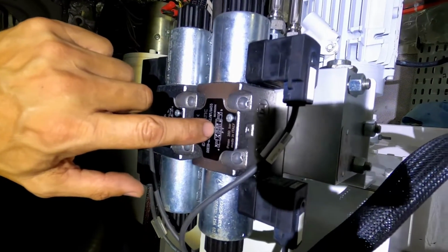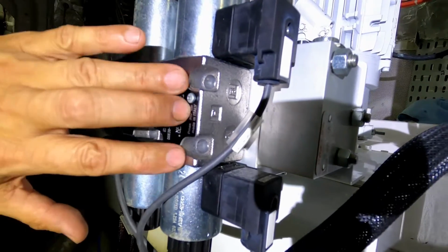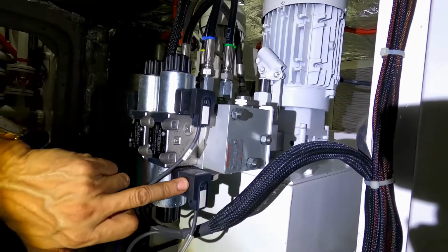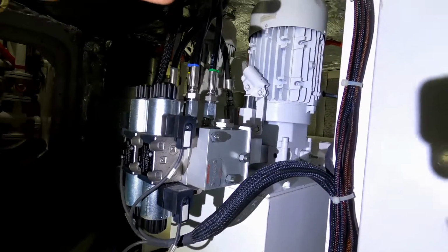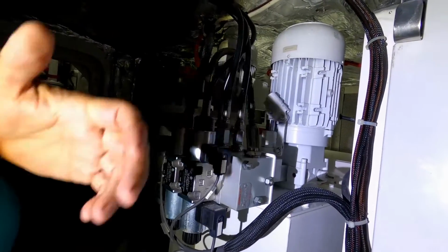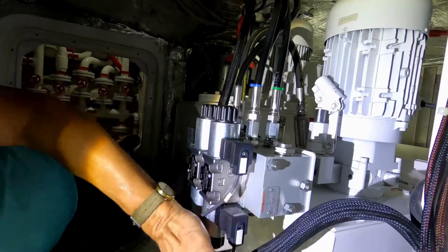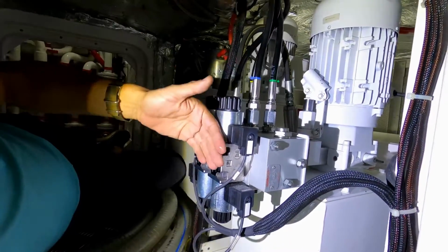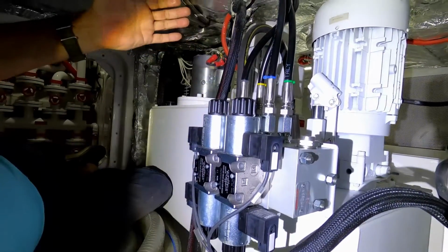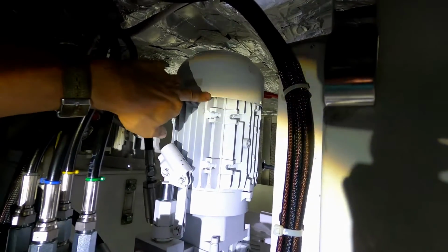The central position is neutral, position for up, position for down, and this one in particular is controlled for a couple of solenoids. The solenoid receives the signal from the control, the push button on top. It is for a windlass, or from the control in the console. You have one servo valve for one element, probably bow thruster. You have another one servo valve for the garage door, and this motor is an AC motor.